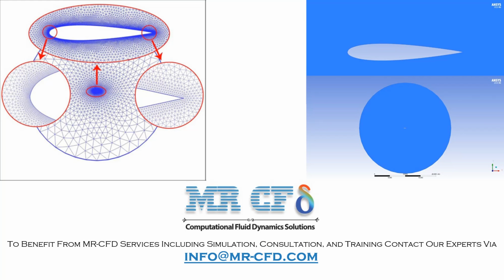The present two-dimensional modeling is done by Design Modeler software. The coordinates of the airfoil points are imported in the software, and the solution domain is a circle of 10 to 12 times the radius of the airfoil chord.